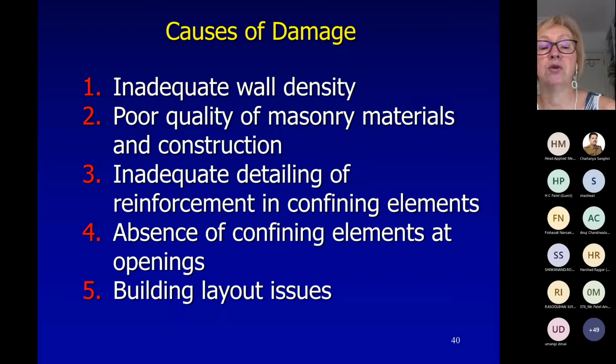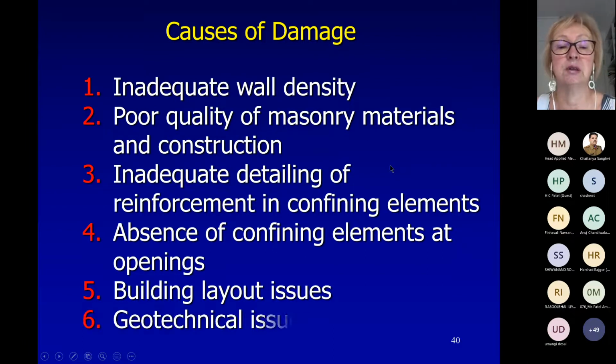In many cases, there was absence of confining elements at particularly large openings, such as doors, and there were some building layout issues also observed. But I would say these first few reasons are most predominant. And there were some geotechnical issues.